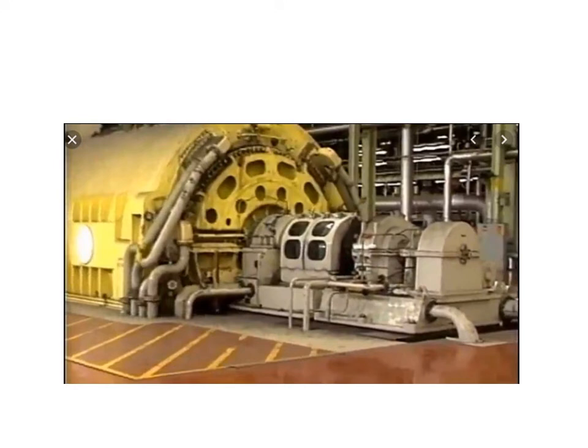So this is the setup of the synchronous generator. It is a very large, very big machine which generates a three-phase AC signal, and many applications require the frequency of the AC supply to be constant. Constant frequency of generated power can be obtained only if the generator runs at a constant speed, called its synchronous speed. Hence the name synchronous generator. Large-size generators are also called alternators.